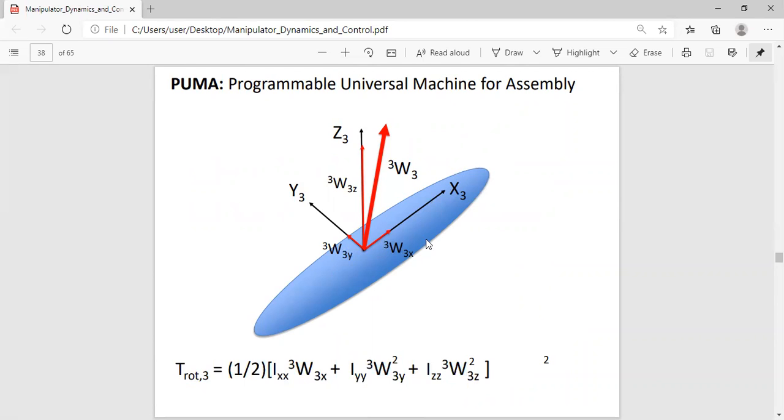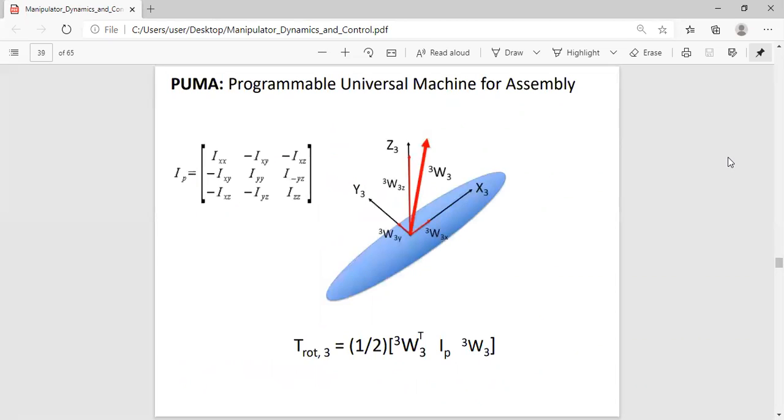You do that, and you can capture the full rotational dynamics of the system, and then you can continue on and do the rest. You can do it like that. You don't really need to do this. Most likely in SolidWorks, you can just provide your moment of inertia about your principal axis. So you'll ignore the rest, and you'll simply have Ix, Iy, and then Iz, right? If these were your principal axes.